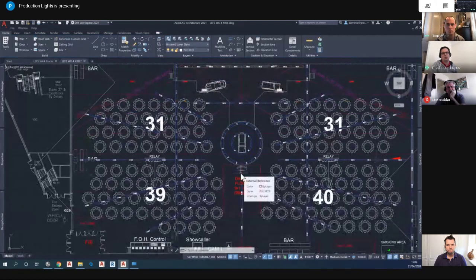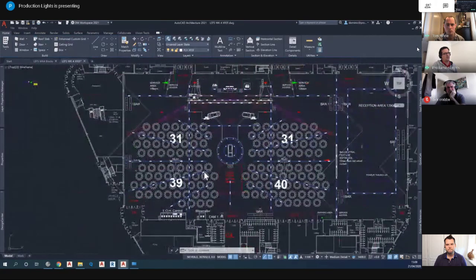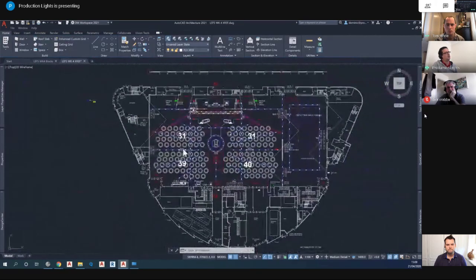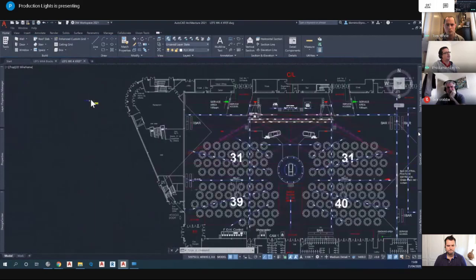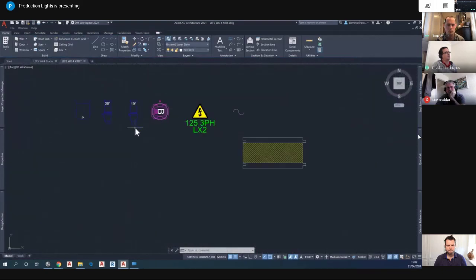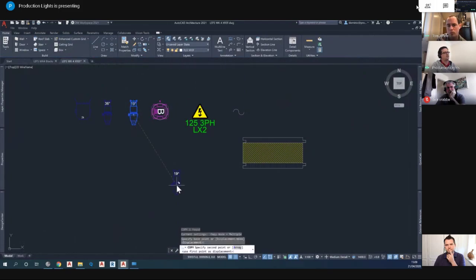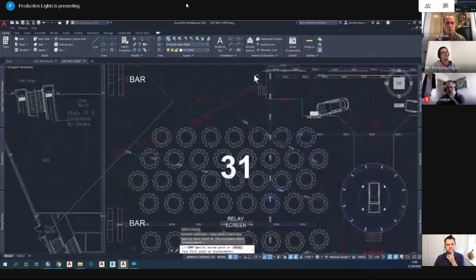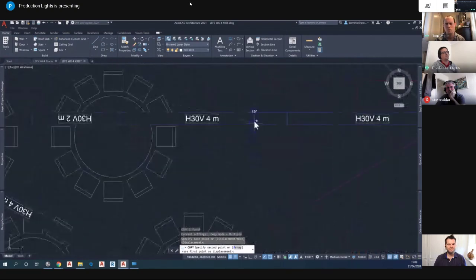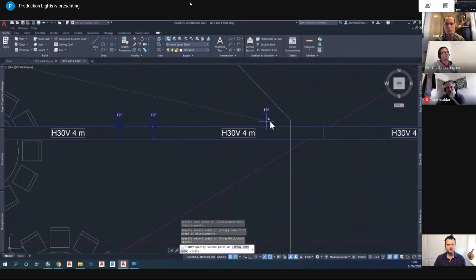And as we spoke about before, it will keep the drawing nice and light, and you can interact with the main designer, say Tom, and just send a lighting layer back again. So if we then wanted to grab lights, we can put them on top of the reference drawing, which, as we talked about last week, was in the correct place, and just bring them to the trusses and drop the lights in the correct places as we go along. And then you can build your design up.